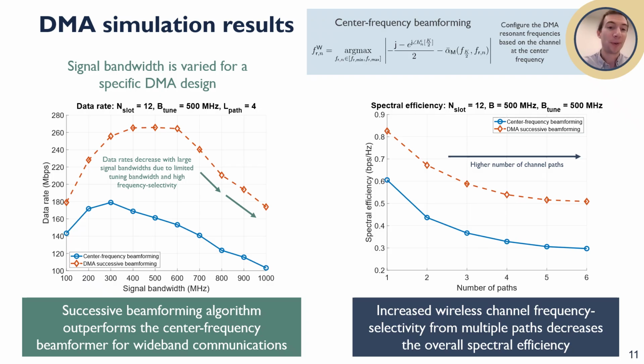Now we'll go over a few simulation results using this wideband beamforming algorithm and comparing against a center frequency beamforming algorithm as our baseline. The center frequency beamforming algorithm configures each of the resonant frequencies based on the center subcarrier frequency of the channel that we configure. So this is our center frequency baseline beamforming algorithm to compare against.